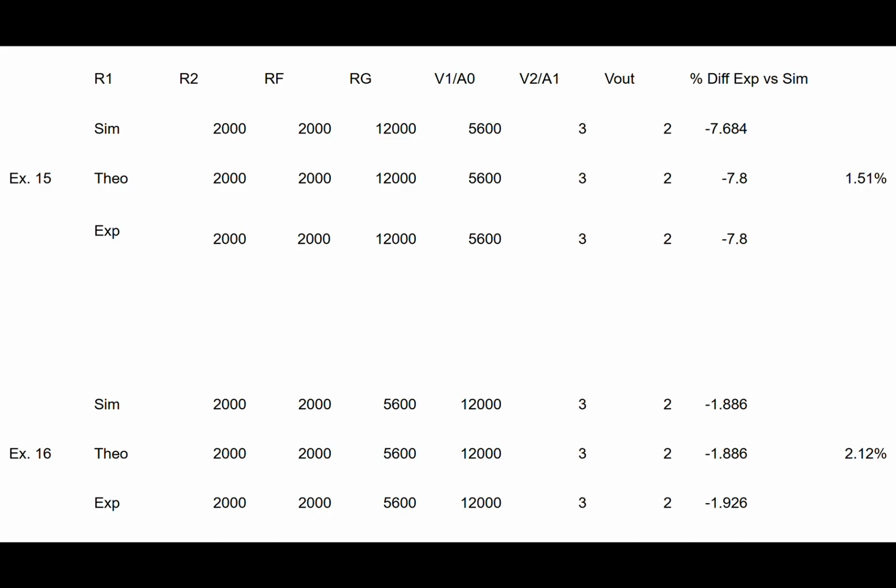Reasons for the experimental margins of error was because the resistors didn't have the exact ideal ratings on them. Some of them had higher tolerances, which led to different voltage drops in the calculations. And also the breadboard and wires may have had some hidden inductances or leached some current out of the experimental data. So yeah, thank you.